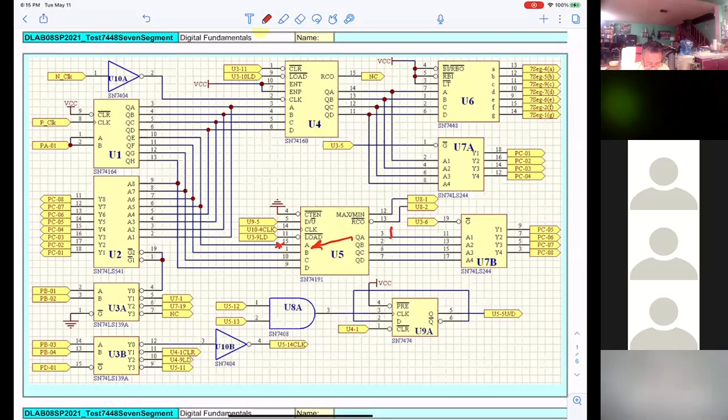Now, my question is, you get 1 here. What can you do? Check the load. Okay, you say, okay, I go to pin 11 here. It should be 0. Let's make sure I get 0. Okay, now you get 0. What next? You get 0 at the load, but you still get 1 on 15, which is wrong. What do you mean wrong? Input is correct. 1 is correct. Oh, you said you got a 1 there. I'm sorry, I thought, okay, you got a 1 there.